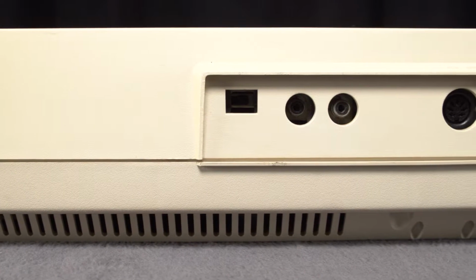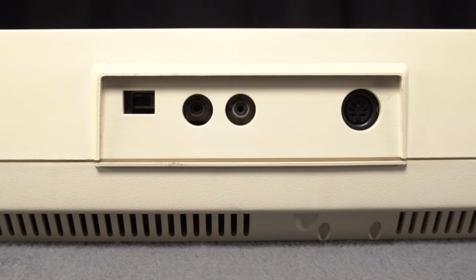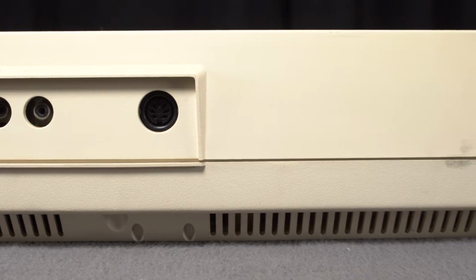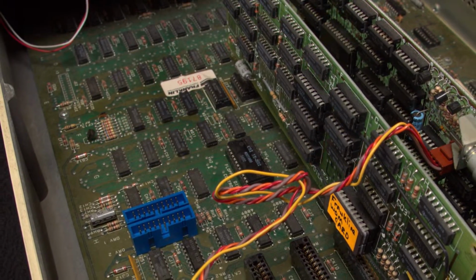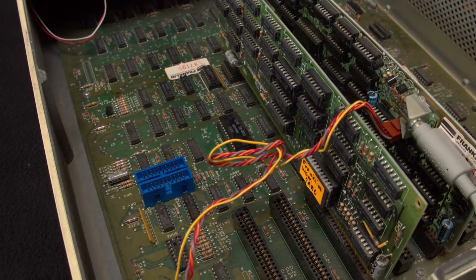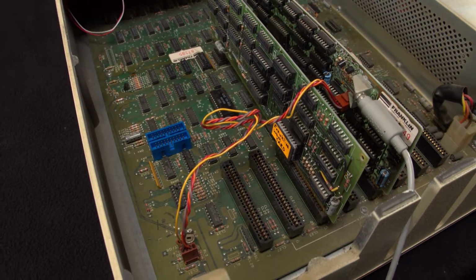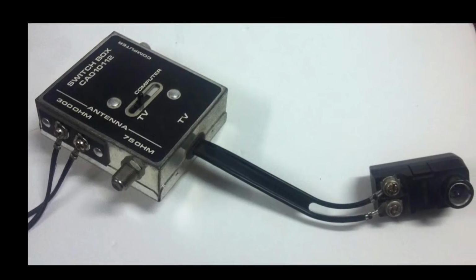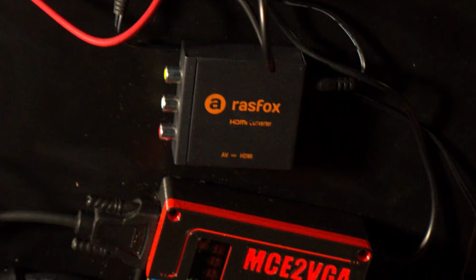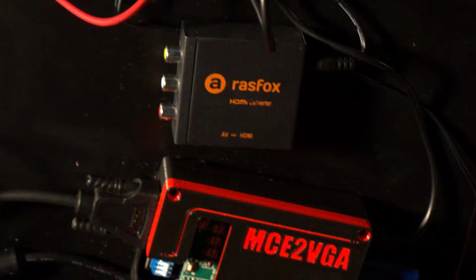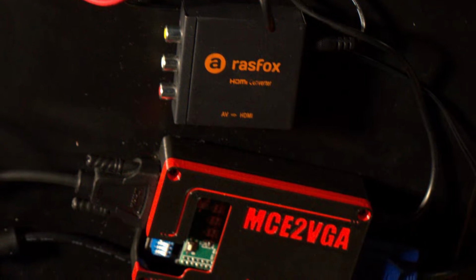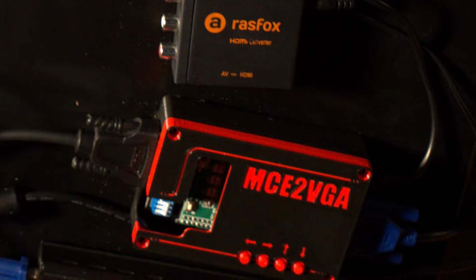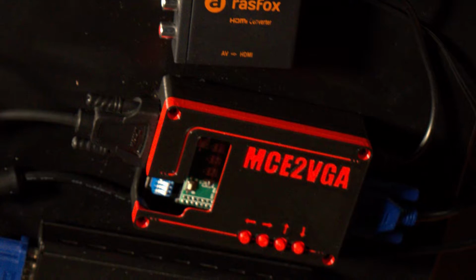In the case of something ancient like an old game console or an early computer system with an RCA RGB output that follows NTSC standards, we need to first convert it to a digital format. RGB is an analog signal, which means that an analog to digital converter can scan, sample, and digitize it even if the information doesn't make sense. The analog to digital converter might be programmed to screen garbage signals out though, so it can be helpful at times to have an old analog playback device on hand for those times when things aren't working and you get nothing but a black screen.